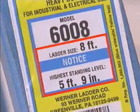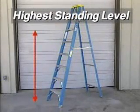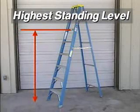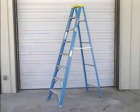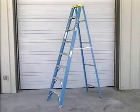Plus, the recommended highest standing level of a stepladder is less than the ladder's total length. The recommended highest standing level is the vertical distance from the uppermost rung or step that the climber should use to the horizontal plane of the ladder base support, with the ladder properly positioned. So, make sure that the ladder you choose is long enough to allow you to safely reach the work area.